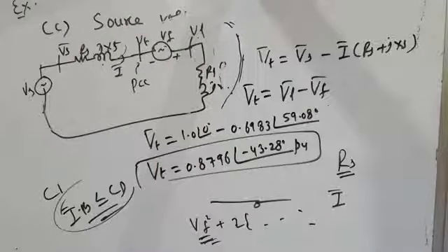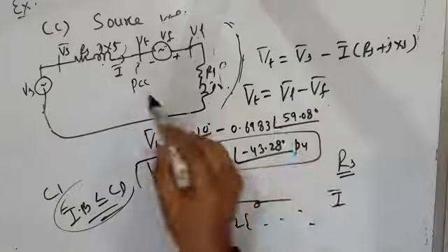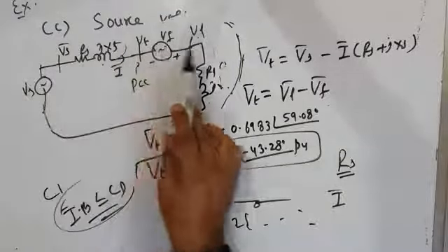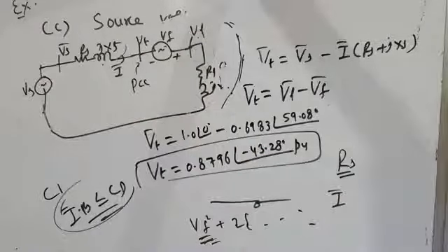We also found that the effective source voltage is not Vs but Vs plus Vf, and that still leads the load voltage by a certain phasor angle. Power angle delta is still positive, so that power still flows from source to load. So this voltage regulation problem, we have understood how a DVR does it.